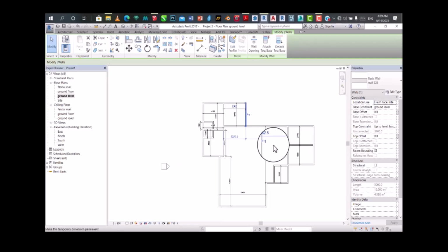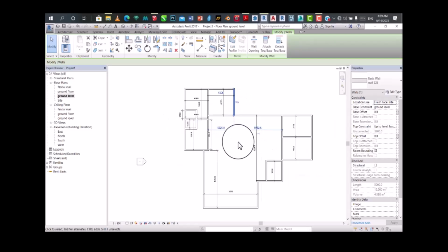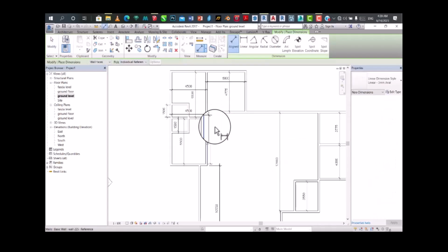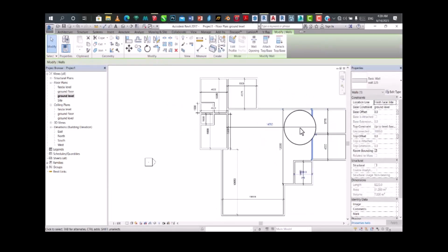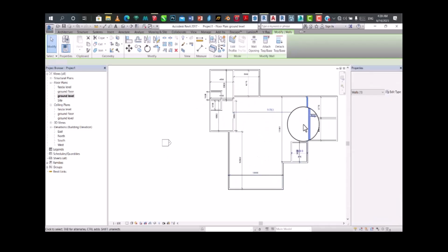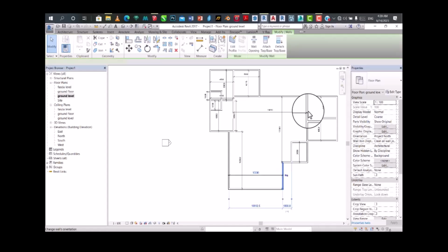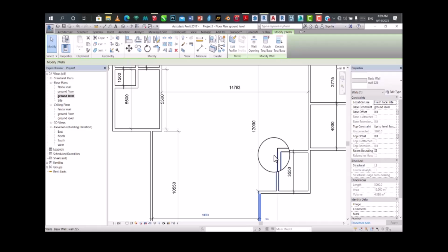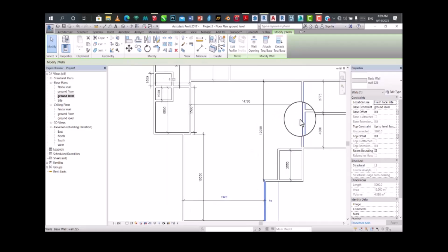Alright, so from here, okay, we don't have any dimension placed there. You come here, click a dimension, place it here. Okay, so sorry, you click on this wall. Okay, sorry, before we edit this, we need to move this, because if you edit this one, the walls will be conflicting. This wall will actually enter inside here, and Revit will never allow that. Let me show you for you to see.